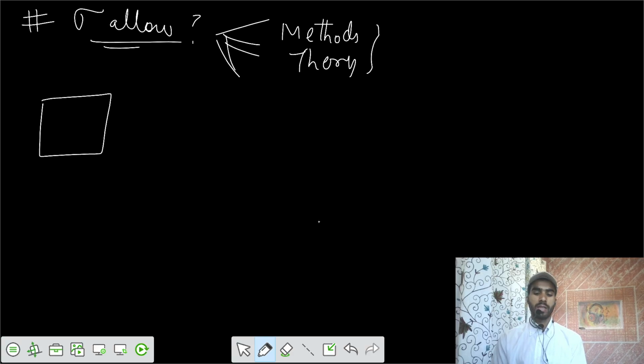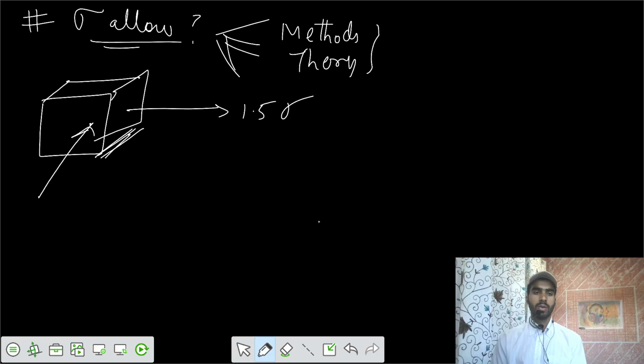Let's say the state of stress is that we have 1.5 sigma tensile, compressive minus 0.5 sigma, and on the top we have positive tensile sigma. Then you have to say, based on the different methods, which method would give you tau allowable, and among those the sigma allowable that is lesser, we will take as the final value.